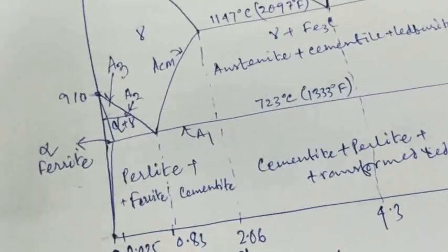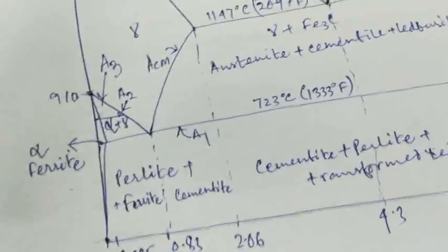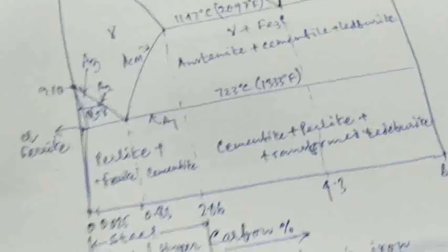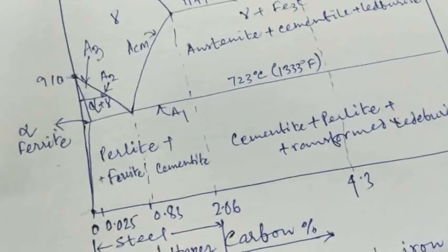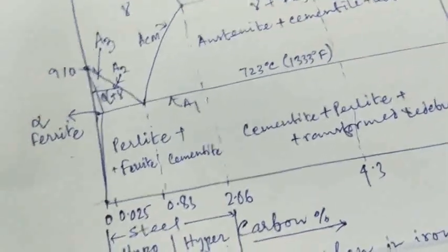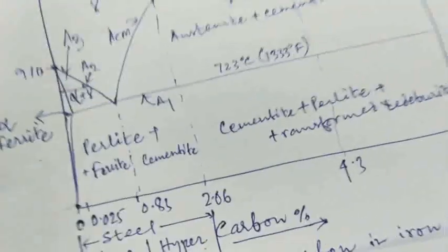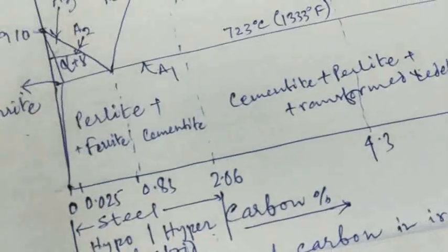After isothermal holding, it is slowly cooled in the furnace to about 500 degrees centigrade, then taken out for air cooling. It has the advantage of a short period, uniform spheroidization and easy quality control. Reciprocating spheroidizing annealing is another type of spheroidizing annealing process.